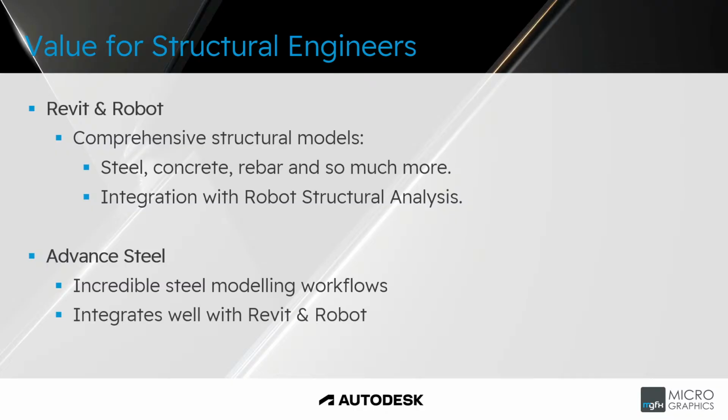Advanced Steel also integrates very well with Revit and Robot. At this stage, Revit's steel workflow is nowhere near that of Advanced Steel. So it's worthwhile building your steel model within Advanced Steel and then exporting that to Revit and doing the rest there, such as your concrete, wood, etc.